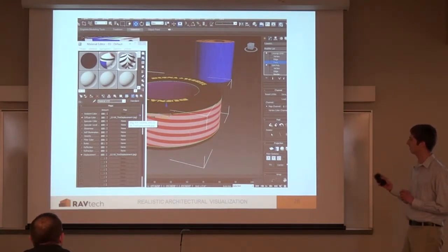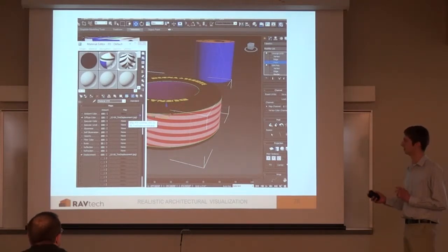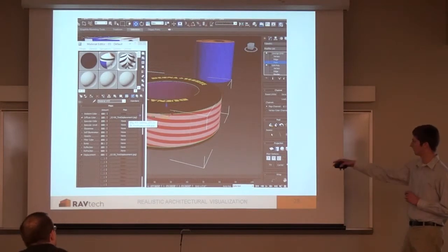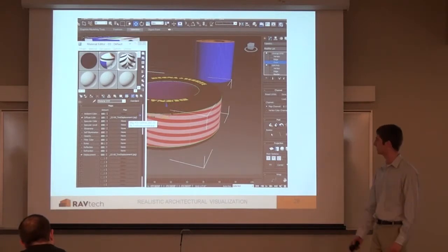This is where I found that the materials really make or break the realism of your image. We found that a lot of materials, if you're not careful, come in way too glossy and reflective, kind of like that picture frame in Max's bedroom. If you're looking down there, there's usually a glossiness slider or reflectivity. A lot of times things come in way too glossy, and you'll have to make sure that you keep that toned down a bit, because you want light to bounce off of surfaces. You don't want to be able to see your ceiling reflected off your floor. It's not made of a mirror, it's just tile.